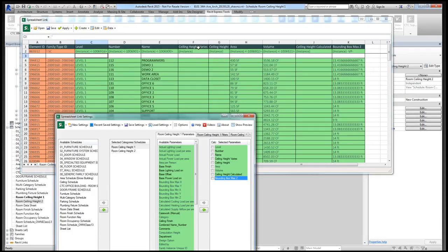Ceiling height varies I added in as a yes-no parameter in Revit as a project parameter. It doesn't matter where you group it. Ceiling height varies as a yes-no parameter. I pre-built that. Ceiling height, I pre-built this as well, and I made it as a text parameter. That's key. This is a text parameter in Revit. Excel doesn't care. Excel couldn't care less of text or feet and inches or whatever, so that doesn't matter. But I did make this ceiling height as text.